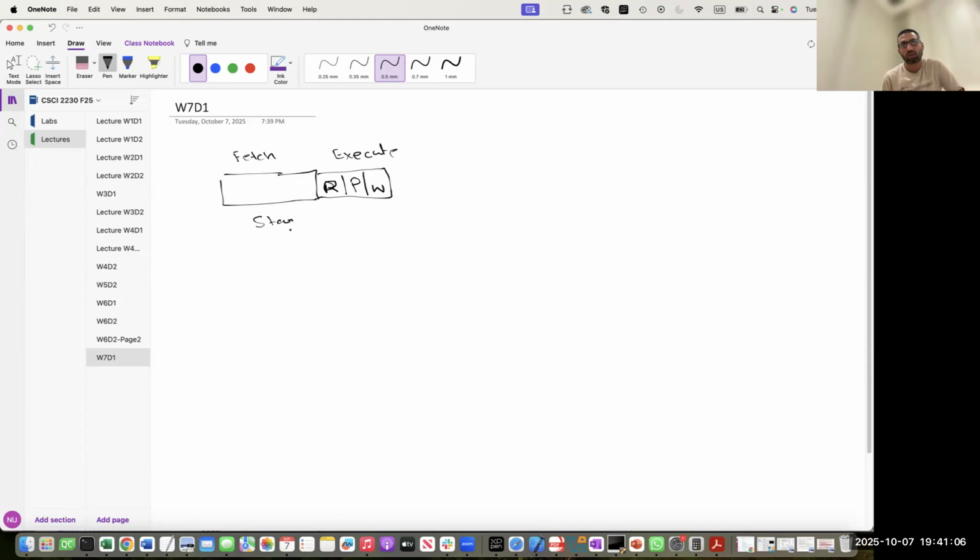So since it is a pipeline processor, it has 2 stages, stage 1 and stage 2, right? So what happens, let's say this is your timeline. Initially you have only one instruction, which I'm naming as instruction 1 in the pipeline. Let's say your program is a sequence of instruction 1, instruction 2, instruction 3, and then you have branch not equal, and you are putting a label, which I'm naming as L.